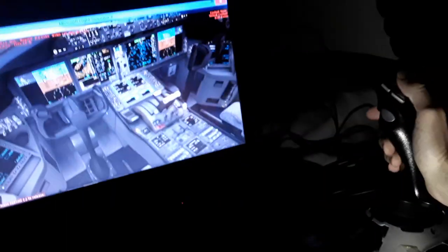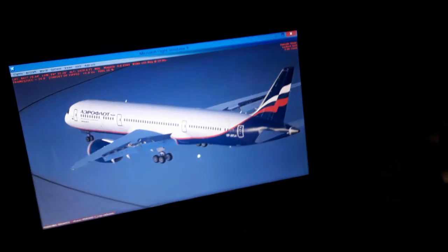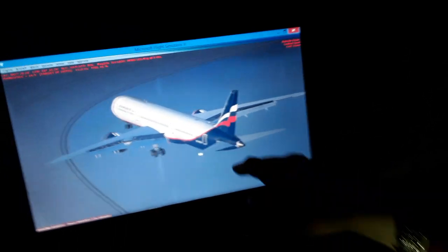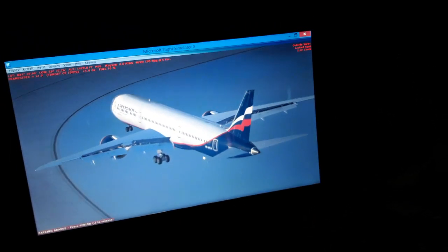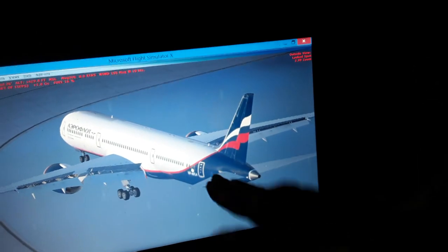So you can trim like that. You will see the effect. The horizontal tail of the aircraft will be moving up and down. This is the trim function, the whole surface usually, or just the elevator in some aircraft. So you can climb, descend. You use also the elevator, climb, descend from the side stick.